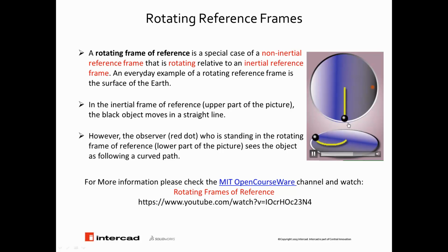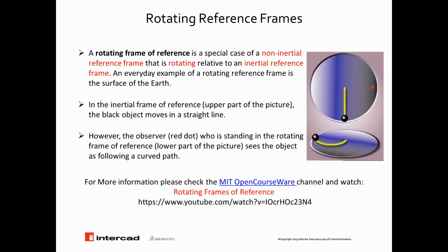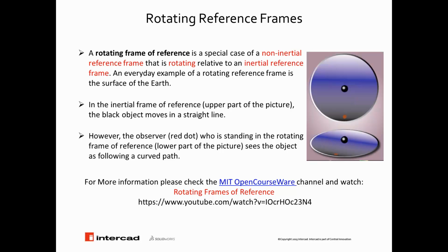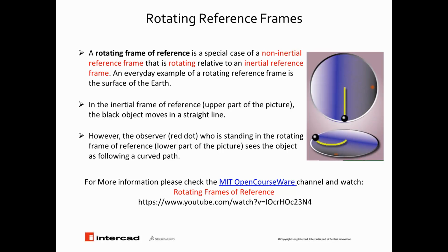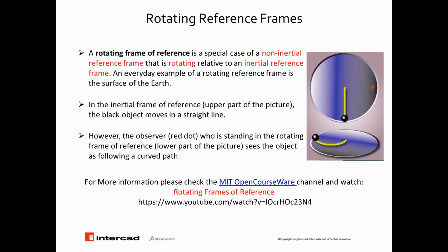This is called a rotating frame of reference, and this is a technique most CFD software employ to turn the very complex problem of unsteady and highly turbulent flow around the blades of turbomachine components into a more steady state problem.